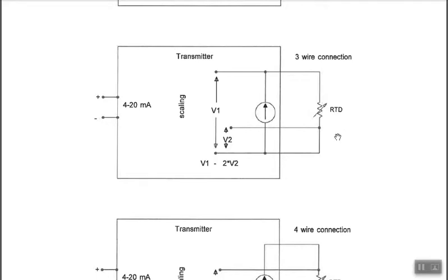You can do a 3-wire RTD connection, which means you'll need the 2 wires that come to and from the RTD that carry the current, so the constant current, and here's the wire carrying it to and from. So those are 2 of the wires. That's the 2-wire connection. Then just one more wire, a 3rd wire, can come out here to this point, and what you're going to have is a voltage that you can see between here and here that is representative of the IR drop that you're looking at from one side.